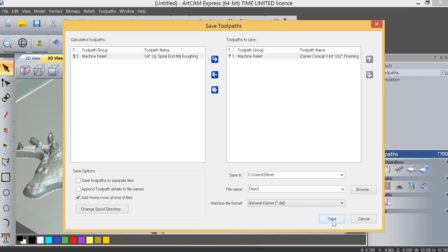Of course, at that point, it's important that the material not move, so the material needs to stay in the machine during that change. And so it will then register the second tool perfectly on top of the first tool, and we will have created the Dear 3D model as a two toolpath operation. And that concludes the training module on the importing and machining of a 3D model.